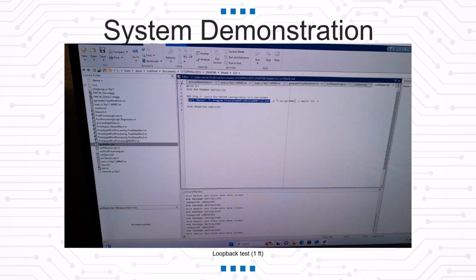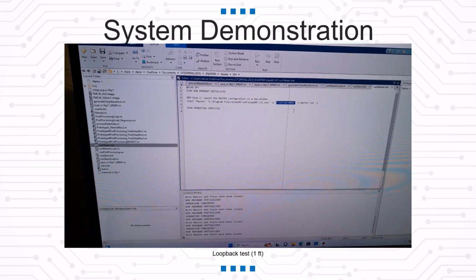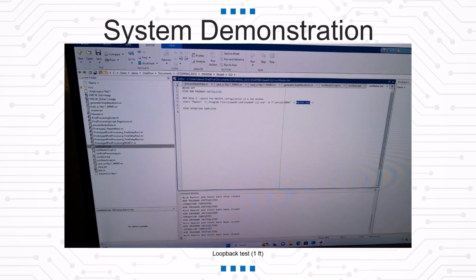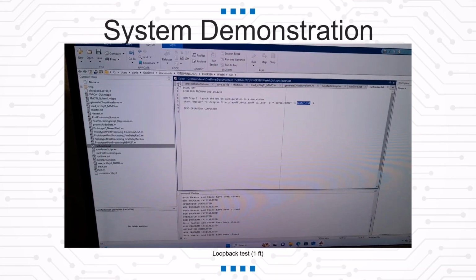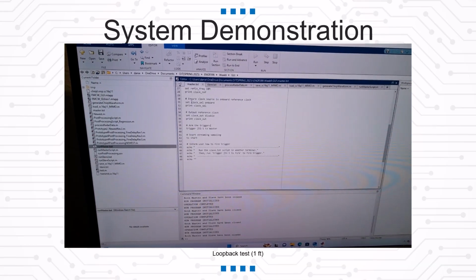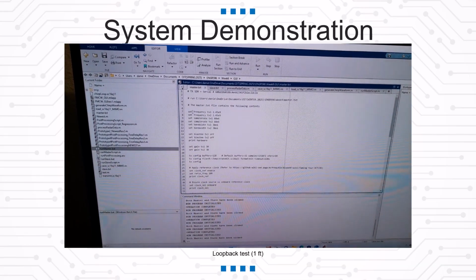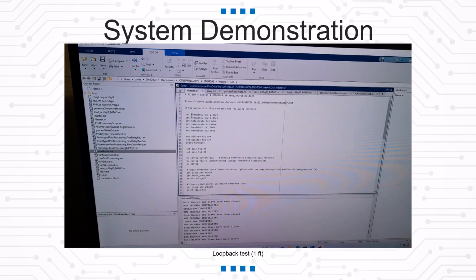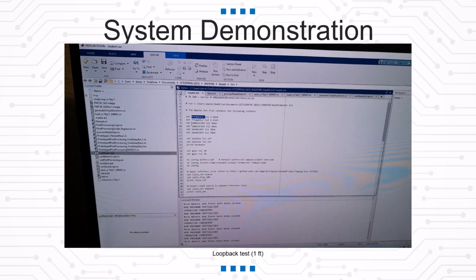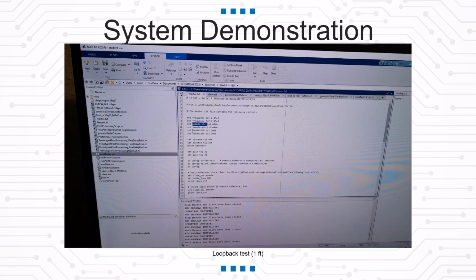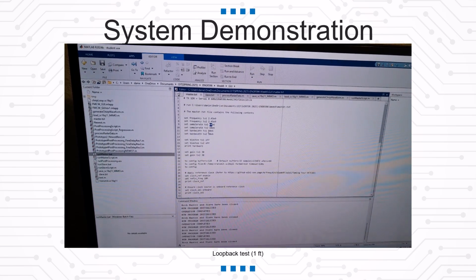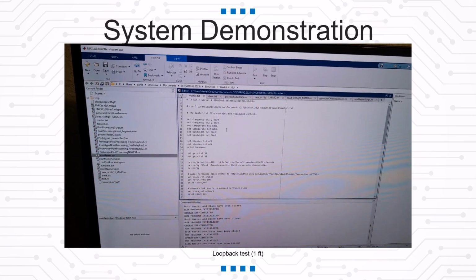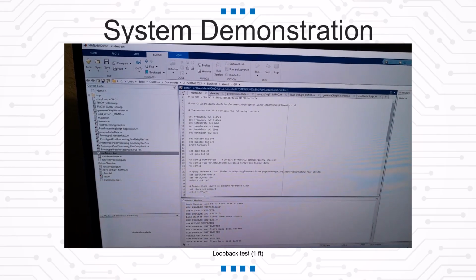It opens up the master based on the serial number, and then it runs a script within the bladeRF command line interface. That script just sets all the parameters, right? So the carrier frequency, sample rate, and bandwidth. Notice that the sample rate is twice the bandwidth, and that's the Shannon-Nyquist theorem.